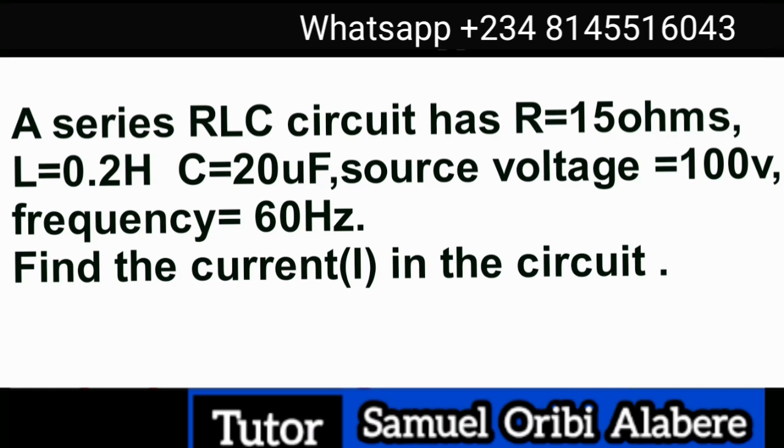In today's video, we'll be looking at the problem below. This problem states that a series RLC circuit has R equals 15 ohms, L equals 0.2 Henry, C equals 20 microfarad, source voltage equals 100 volts, and frequency equals 60 Hz. Find the current I in the circuit.